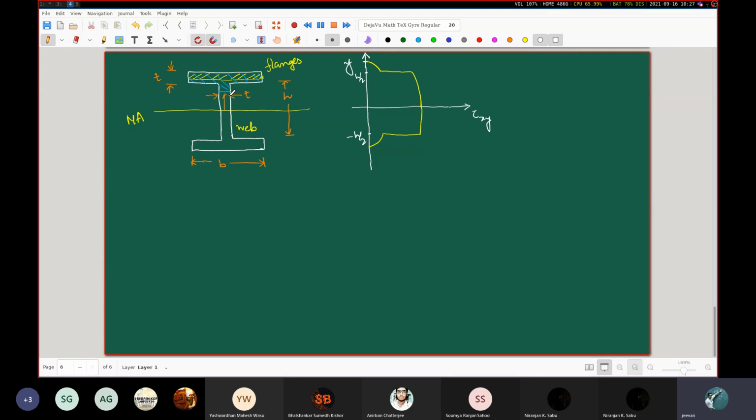So what I actually mean to say is that this neutral axis is directed along the z-axis. Okay, the z-axis is like this. So along the z-axis, there is going to be a certain variation in the tau xy, just like there was variation in the tau xy along the z direction for the rectangular beam also. So this is some kind of an average value.